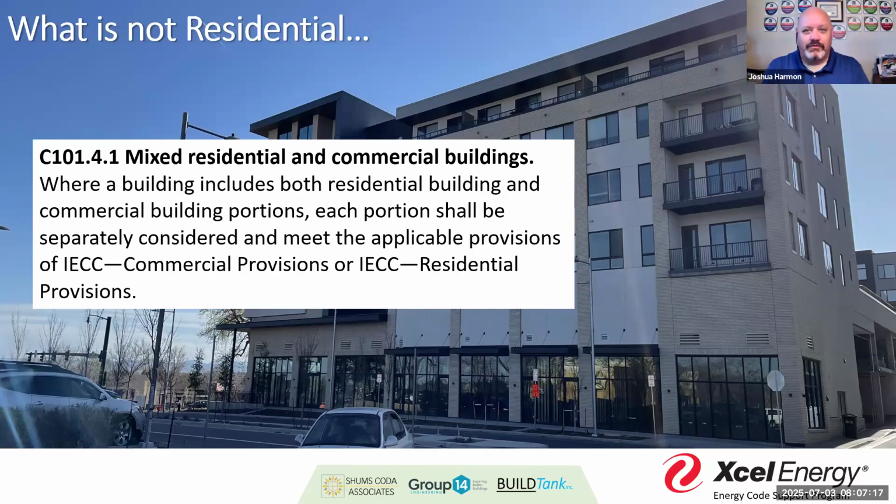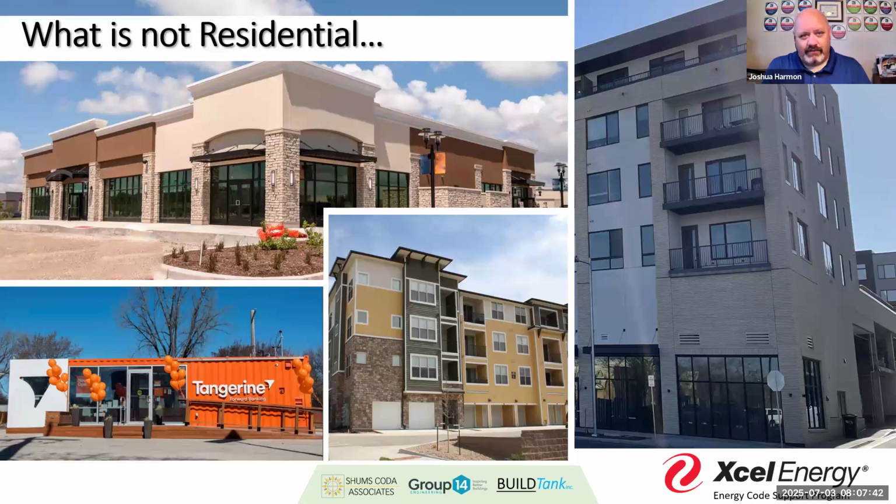It got more interesting as we got into it, because it was actually a metal building, right? And now it's a metal building, and a metal building is going to be treated differently than a traditional wood frame building. And so that's where we have to understand the type of construction we're dealing with to really get to the right thermal resistance values. And again, that's part of walking through the system, understanding when it has residential components. Some things are clearly not residential. They're office spaces, convenience stores, hospitals. And so those are going to be a little bit easier to follow.